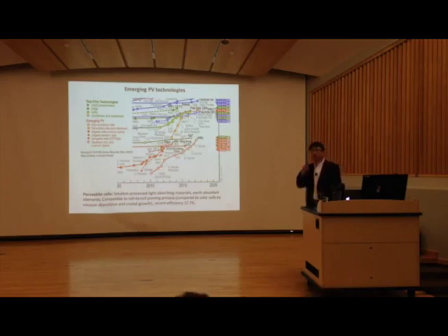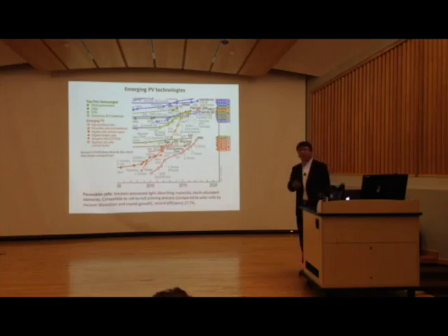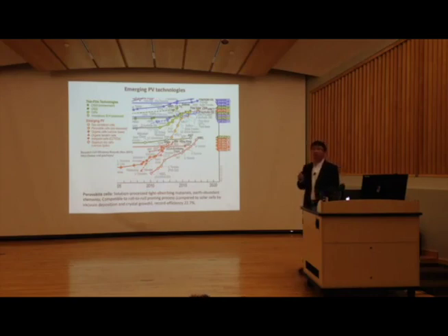Yeah, I think it's a good question. Scientifically, there is a lot of exciting news for graphene and other types of materials. I want to raise this important point. For a silicon solar cell, the silicon has a band gap of 1.1 eV. 1.1 eV is equivalent to a wavelength of about 1100 nanometers, which is already in the infrared region. So silicon already harvests a great amount of infrared energy.